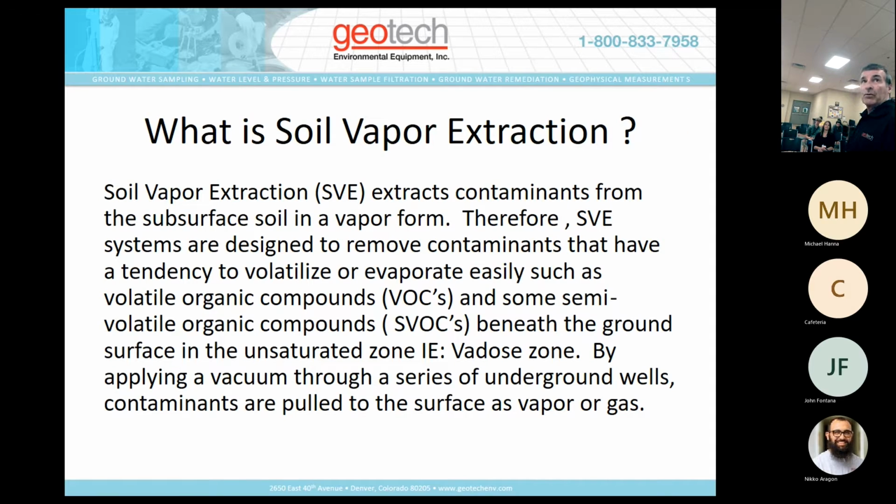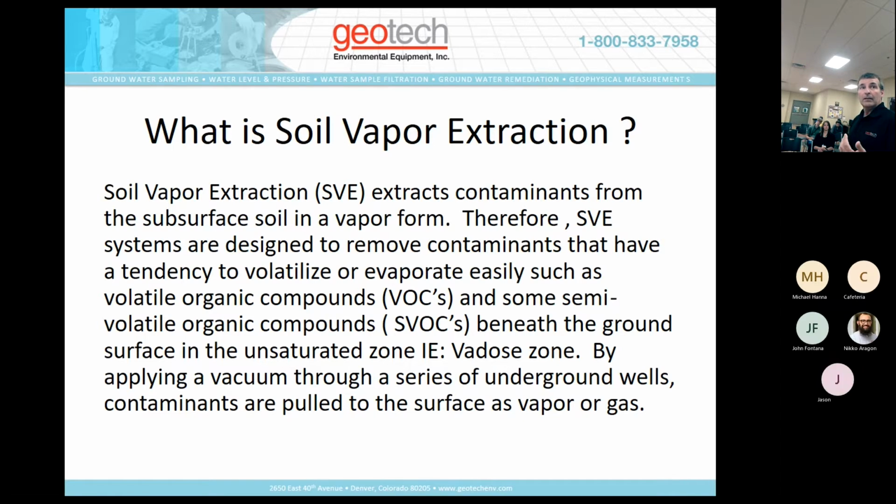So what is soil vapor extraction? It extracts contaminants from the subsurface in vapor form, and so they're designed to remove contaminants that tend to volatilize, like gasoline, some diesel, and we can also do some chlorinated. Like I mentioned, we apply a vacuum through a series of underground wells, and the contaminants are pulled as vapors to the surface.